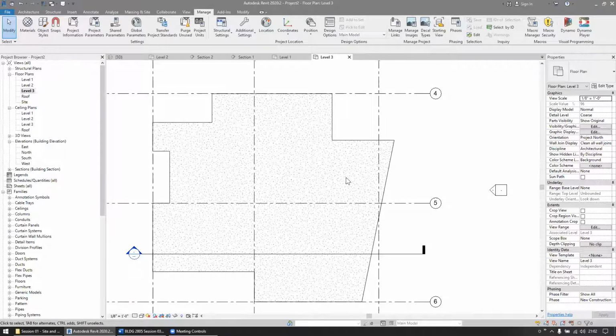So there's going to be some upstand curbs to prevent ingress of water into the building. So yes, those curbs could be drawn as walls. But man, oh man, what a pain in the butt to get all the walls to join nicely if you've got concrete wall curbs drawn. So I recommend highly that if you are doing a slab plan in the future, whatever height of curb you need, draw it as a floor object.